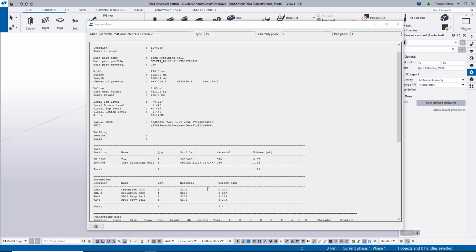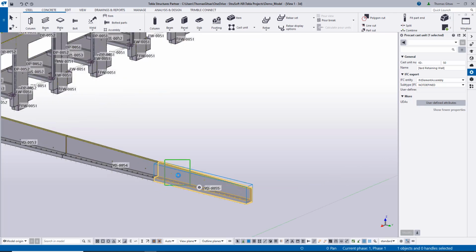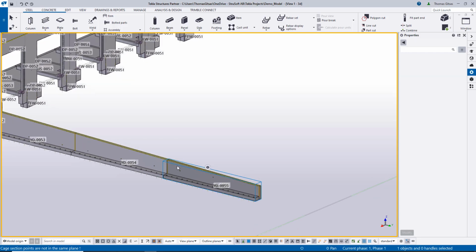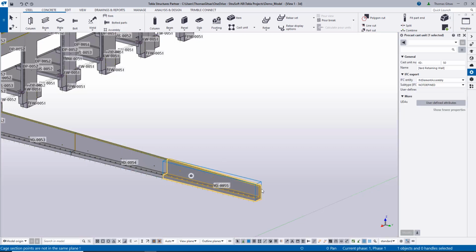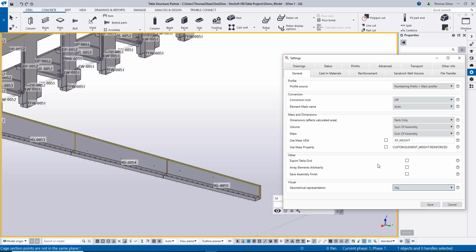Basically, if we use OBJ, this view here will be the same as the one that you have from Tekla in the Impact model view. If you use Impact, then the profile from Tekla will be translated to the profile from Impact, and the view might be a box of concrete, which of course will not be very nice for you to plan later on. That's why 99% of the time we use the OBJ feature here.